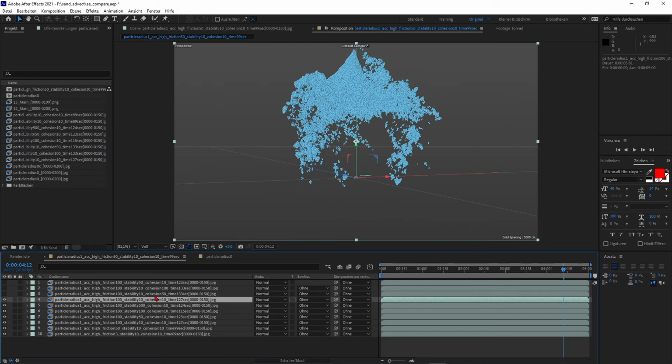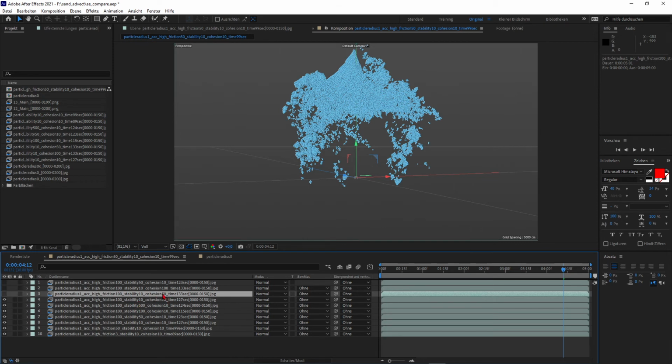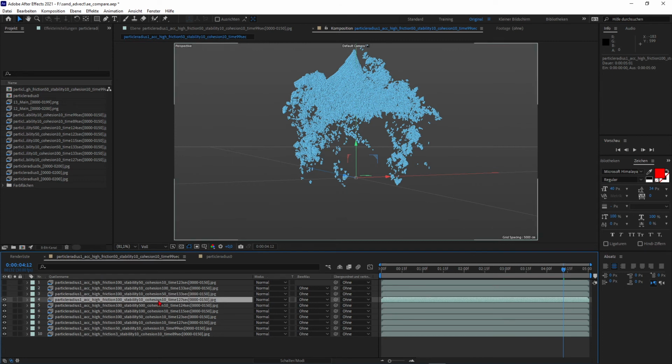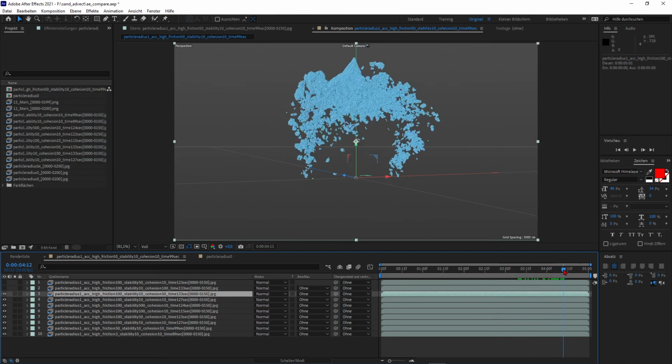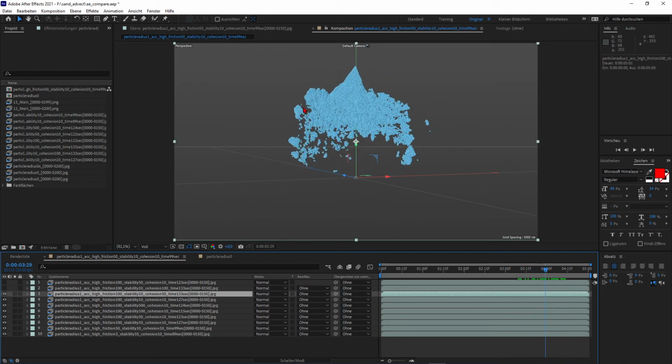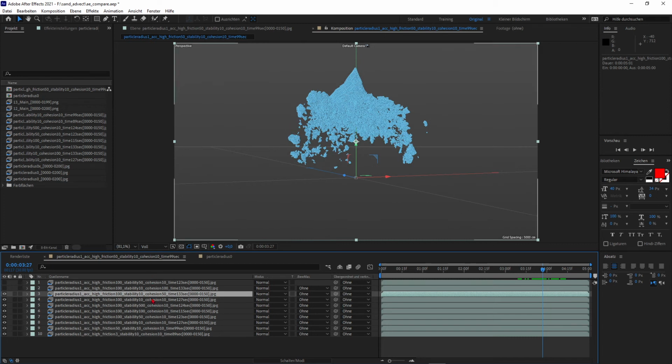And now I change the cohesion. But sadly, I didn't have this knowledge about the sensitive values that Bob Wormsley was mentioning. So they are between 10 and 30 when it comes to cohesion. But anyway, we should see a change here from cohesion 10 to 50. All right, and you can see it now. These clumps are bigger.